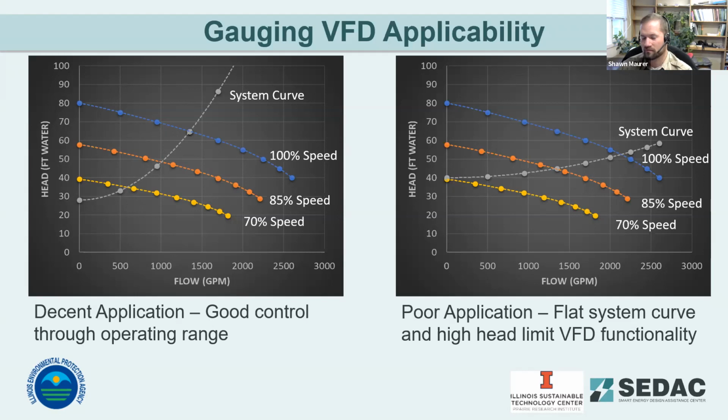If the curves are both relatively flat, even if you have a low head situation where a VFD might be applicable, you're going to have difficulty controlling it, because a small change in head pressure is going to give you a large change in flow rate. It's going to be hard to control to that control parameter of flow.